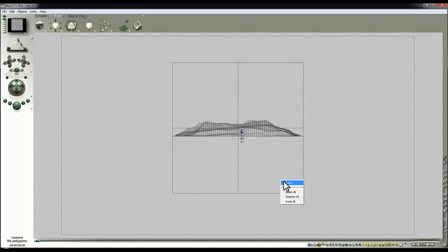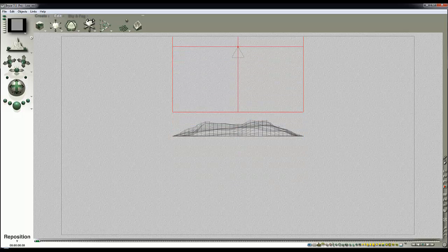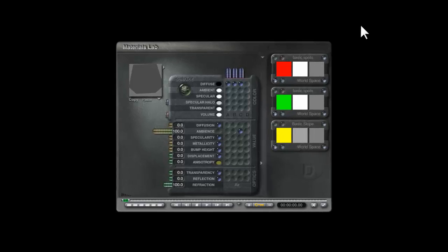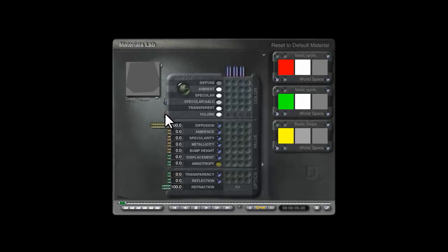Now I select the cube as well as the camera by holding the Control key down and then holding the Shift key down while clicking on the cube, and then lift the pair of them up together so they're above the terrain. It doesn't matter what height above the terrain. What matters next is when I select the cube and not the camera and modify the material, I need it to be reset to default grey, fully transparent with no refraction, and then I can just get rid of the diffuse. Even though I've got no diffuse source in this scene, this is now going to modify the way the camera views the ground, because when it goes through this surface, it changes the normals of the viewing ray, whatever it is that comes from the camera or goes back into the camera.